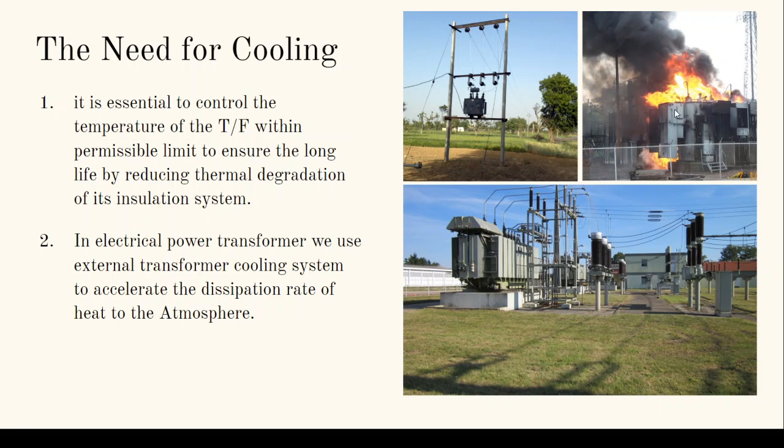Now, in case you don't cool the transformer, if there's a fault, you would have an explosion, and it's filled with oil and is flammable at high temperature. So it's important to control the temperature of your transformer within permissible limits to prevent the transformer parts from degrading and the insulation breaking down to cause an electrical fire.